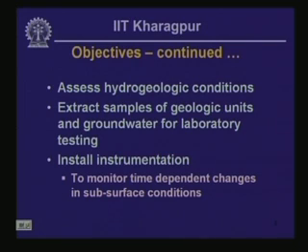We continue with the list of objectives. Subsurface investigation also quite often involves assessment of hydrogeologic condition. What we want to find in this case is the condition of the groundwater within the subsurface deposit underneath a site.